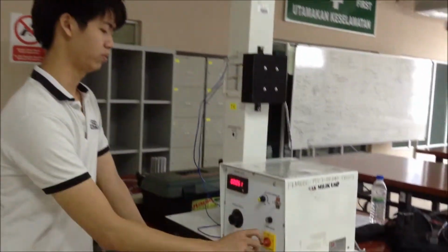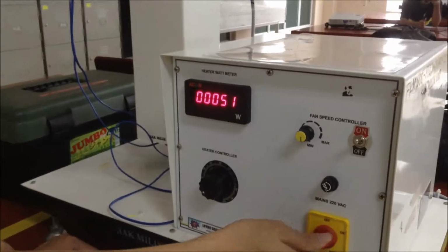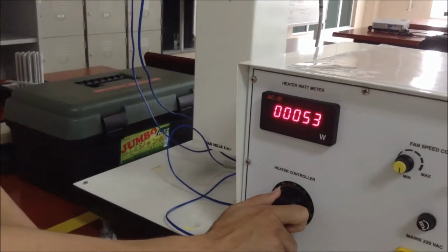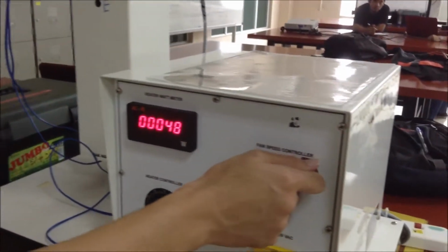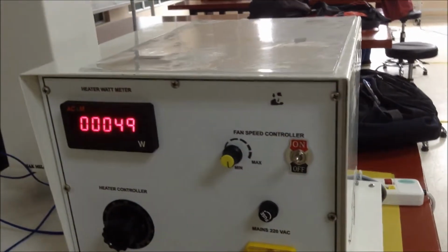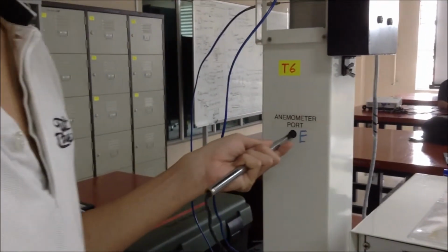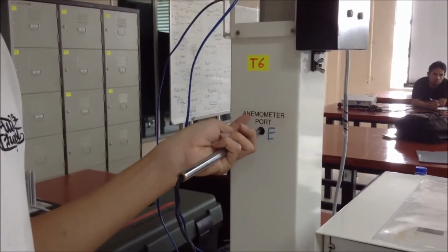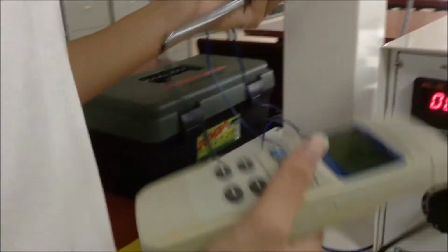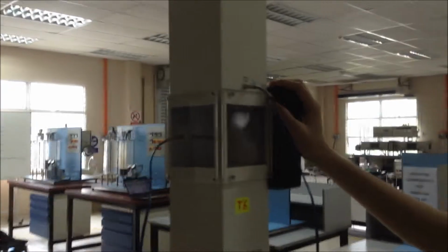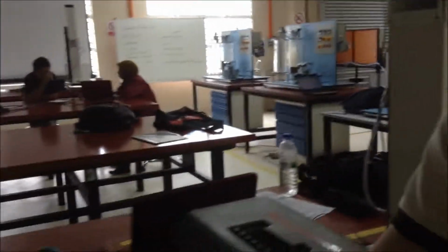So let me first introduce our test rig. First, we switch on the main switch and then we set the constant variable, which is the heater controller, to 50 degrees, and then we will adjust our fan speed from 0.2 to 1.0, and we will test it by using the anemometer and get the result from the anemometer ports. After we have set the manipulated variable, our responding variables will be T1 and T2. So after we have done the flat plate, we will change it to the fin plate